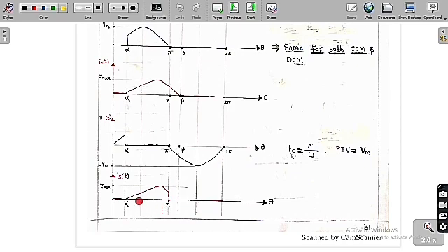So therefore, source current is equal to load current up to here. Whereas from pi to the remaining range, the freewheeling diode is conducting but not the thyristor. So the thyristor is open, and therefore the source current will be equal to 0. Now you can see these two are different graphs. Only from alpha to pi both are the same, but after that this is non-zero, but this is 0. So these two are different graphs because of the extra branches present.